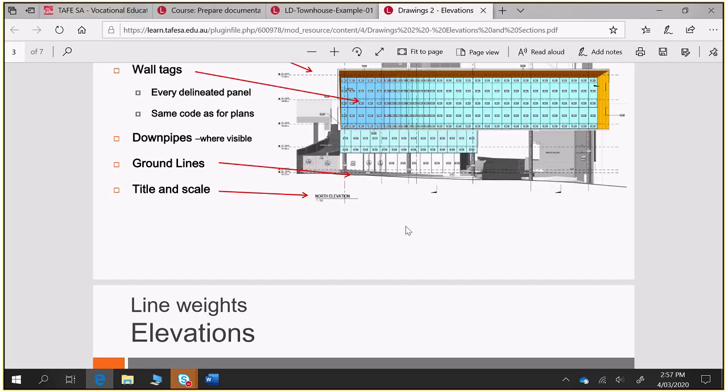And also with Revit, you take a different approach than what you take with AutoCAD. So I would do that sort of thing in AutoCAD, because then I'm grabbing that and straight away I'm drawing a section for showing that my footings are interacting with natural ground there. And so I'm doing some of that work already. You don't do that, you approach things differently in Revit than you do in AutoCAD. So it always comes back to thinking about what do you need to communicate and why.